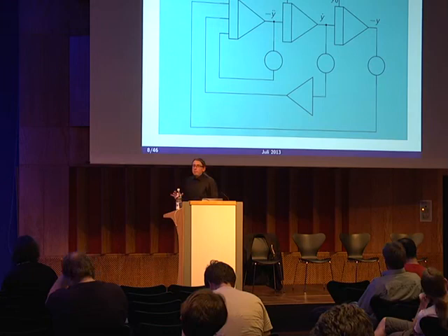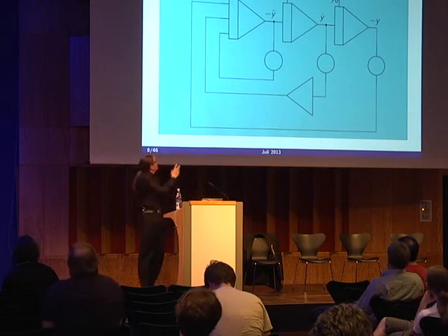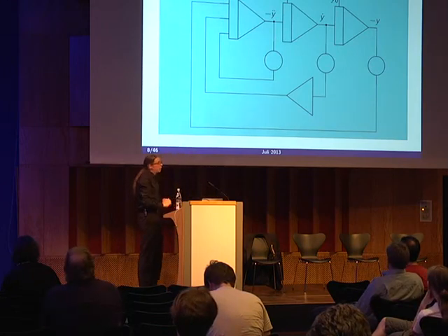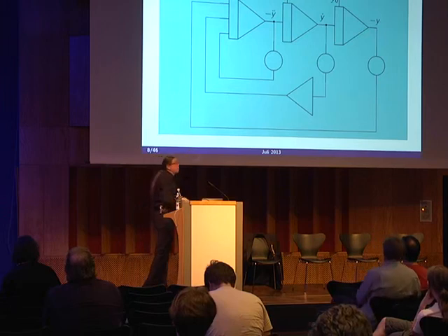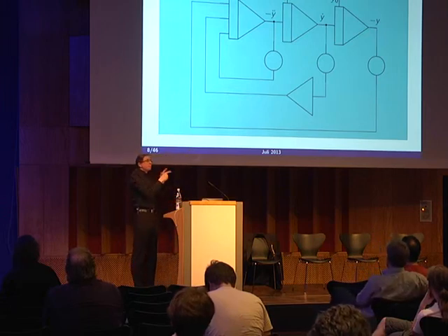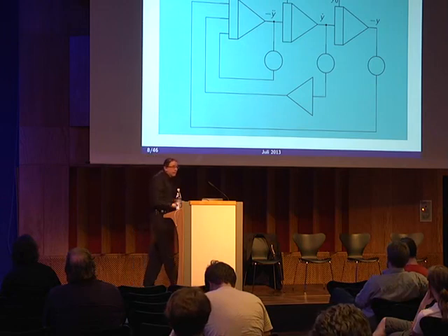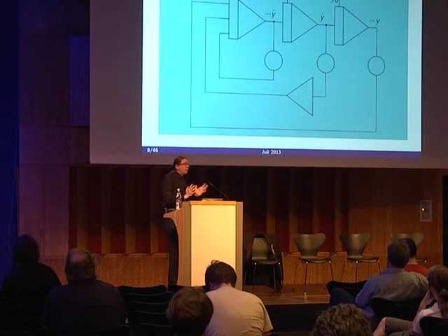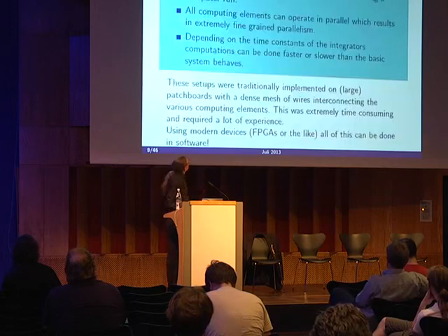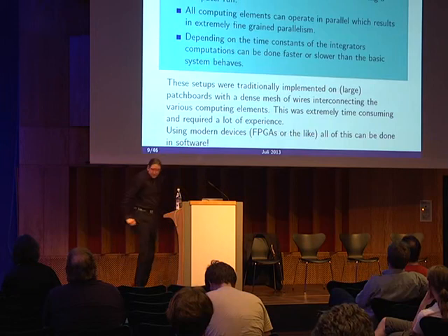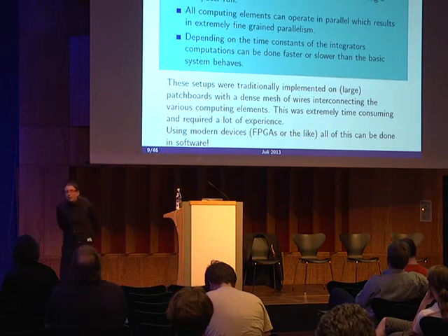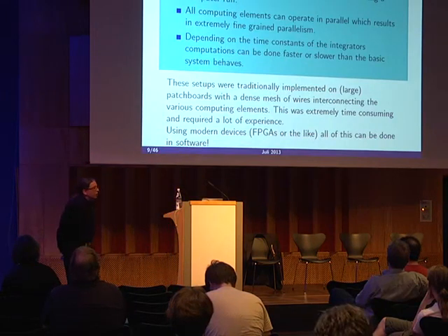Regardless of how you implement your integrators, your summers, your coefficient potentiometers, which are represented by these circles, you can program a machine by diagrams like these, because these diagrams describe the structure of the machine, which will be an analog, a model for the problem you want to solve. That's just a very, very simple example, but I hope you got an idea how an analog computer is programmed.